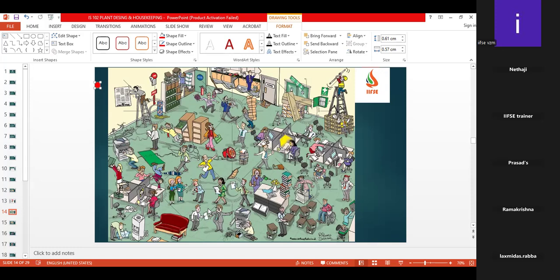On the right side, I request everybody to please get involved and say at least one hazard which you see here. On the right side, improper ladder use, sir. That person, right, we have cleared. This fire extinguisher has been kept as a door stopper. And near the entrance there is also so much metal here. Upstairs, okay, obstruction.